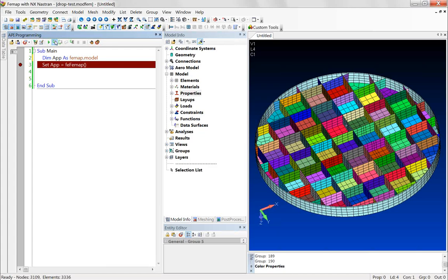So if you've specified density in lbf-s²/in, as is common with English and U.S. units, and you want to immediately know what the mass is in pounds, that's a simple script to do that. I've got that in there, and another one to quickly disable properties. So yes, there are a couple of small, simple scripts in there.